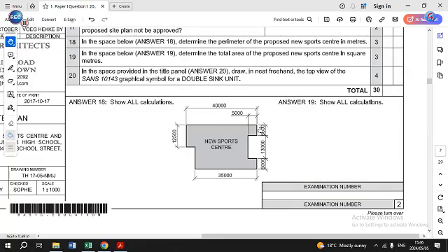So for you to be able to determine this here, you need to subtract 35 meters from the 40 meters that we have on top here, which will give you 5 meters as the small opening, very similar to that side over there. And for you to be able to determine this length here, you need to add up the 6 meters, the 30 meters, and the 6 meters, which is 12 and 13, which is 25 meters, and you need to subtract 12.5 meters from the 25 meters for you to be able to get this length over here. And you have to write in those lengths right in here, so your calculation could be made very easy.